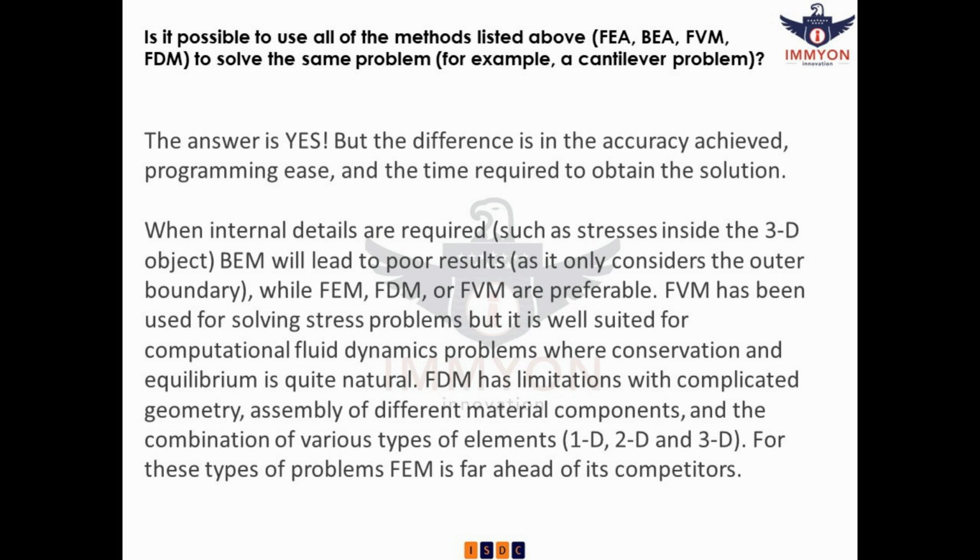When internal details are required, such as stresses inside the 3D object, BEM will lead to poor results, as it only considers the outer boundary, while FEM, FDM, or FVM are preferable. FVM has been used for solving stress problems, but it is well suited for computational fluid dynamics problems where conservation and equilibrium is quite natural.